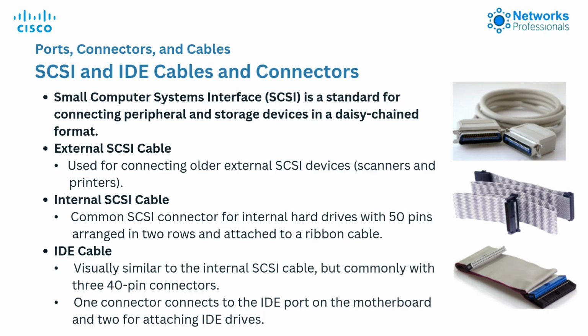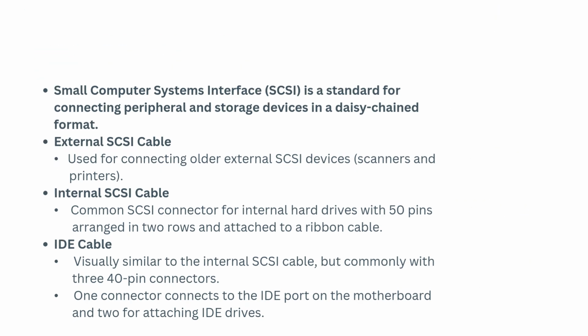External SCSI cable. Used for connecting older external SCSI devices, scanners and printers. Internal SCSI cable. Common SCSI connector for internal hard drives with 50 pins arranged in 2 rows and attached to a ribbon cable. IDE cable. Visually similar to the internal SCSI cable, but commonly with 3 40-pin connectors. One connector connects to the IDE port on the motherboard and 2 for attaching IDE drives.